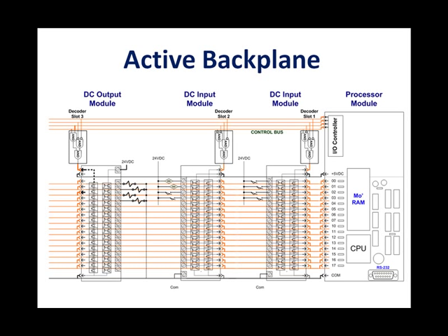It is really a very straightforward, simplistic system when you look at it one function at a time. If you look at this diagram in front of you right now and study it, you will realize that everything external to the processor module, by way of either the control bus or the data bus, is nothing but solid-state switching. You could go to any electronic supplier and buy all of these components to build your own set of decoders, your own set of optical isolator I/O cards, etc. There's no rocket science here, folks. This is a real simple solid-state switching concept.